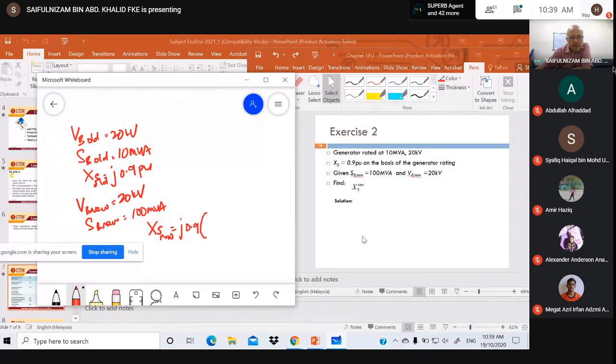So what is kV old? kV new? Same, right? Yes. kV old is the numerator, the denominator is kV new, right? Old divided by new, multiplied by MVA new, or S base new. What is S base new? 100, divided by S base old. So you get j9, you write.